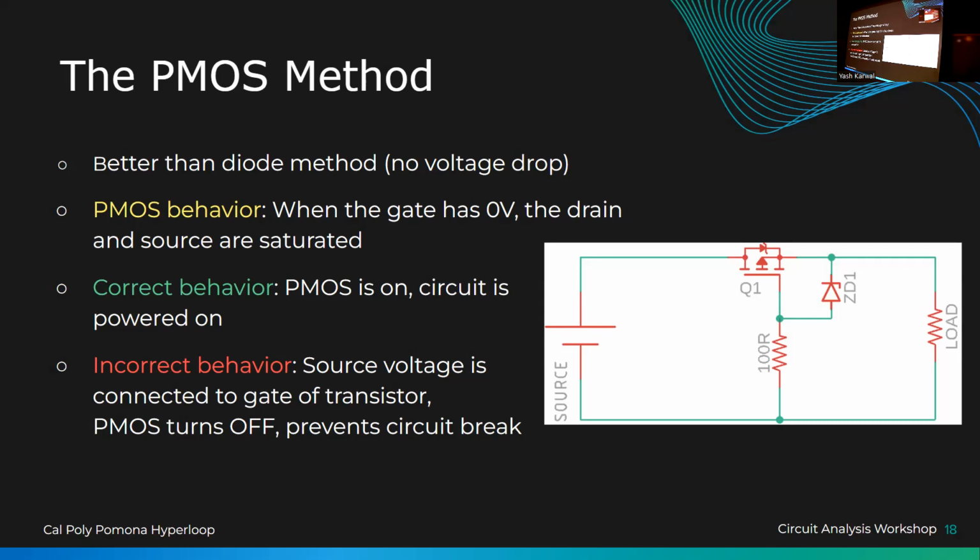So why, when we put it the other way, doesn't it go through? Because like I said, this one has to be greater than the gate right here. If we plug in -5 volts, is -5 larger than 0? No, right? So this one stays closed, and there's no shorting right here.